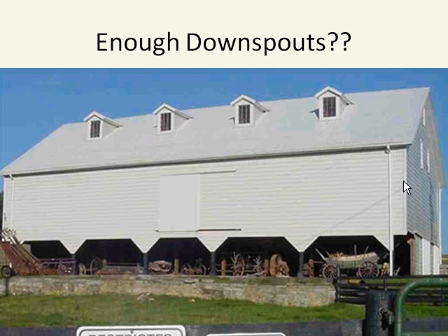So I put this picture in here because as I'm looking at this one, it looks to me like this one definitely wasn't designed as an animal waste system. You see two downspouts on this fairly large building on either end, and this probably wouldn't work if you were designing for a 25-year, 5-minute type of rainfall event.